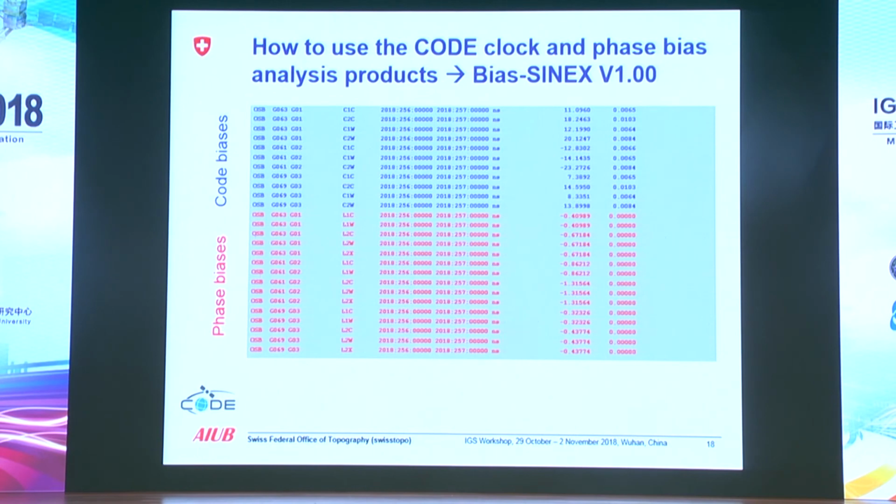And this means for the user, with our approach, you have in blue the pseudo-range corrections and in red the phase corrections, so he just has to decide which observable is involved, independent of whether he is using the Melbourne-Wübbena linear combination or the ionosphere-free linear combination.